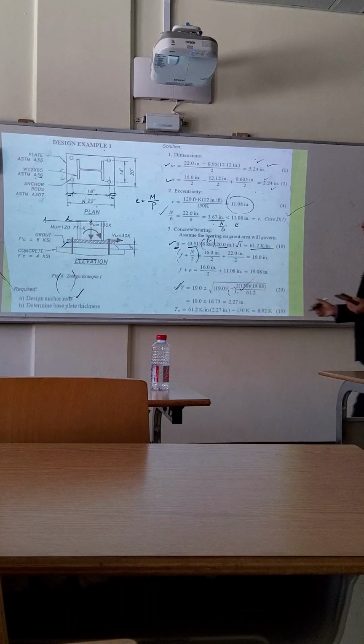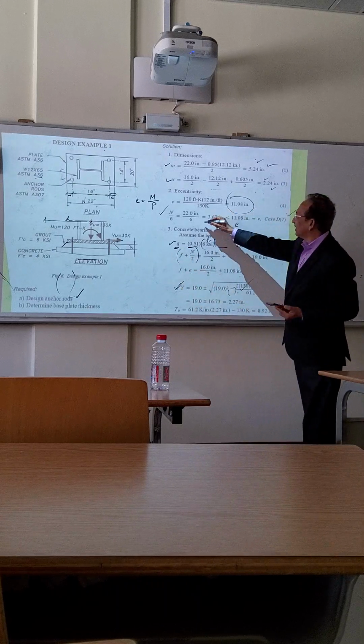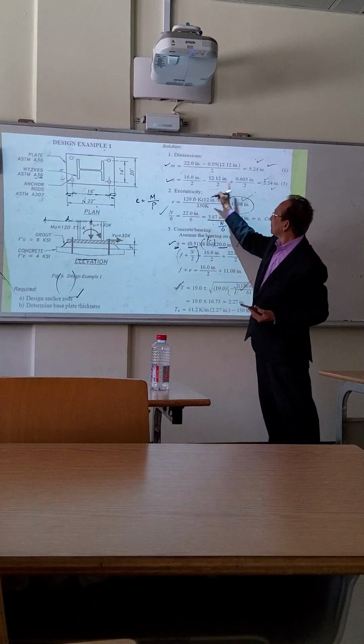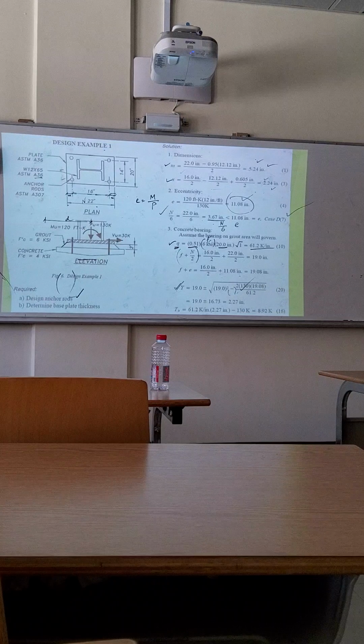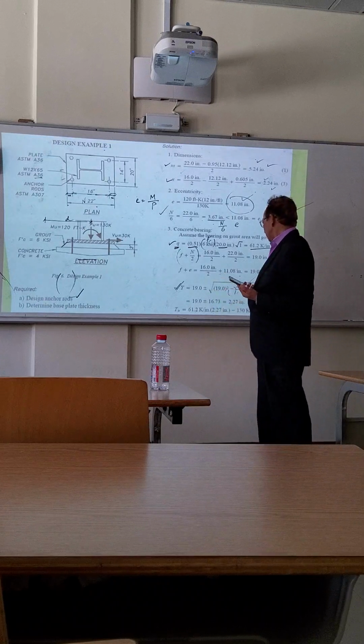Y is the bearing interface. How much of that concrete is being compressed? And that will give you the idea of the pressure on the plate. So we find this value F plus N by 2 and F plus E. E you have calculated here. This is the value of E, and F we have also calculated. So now we find this value of Y.